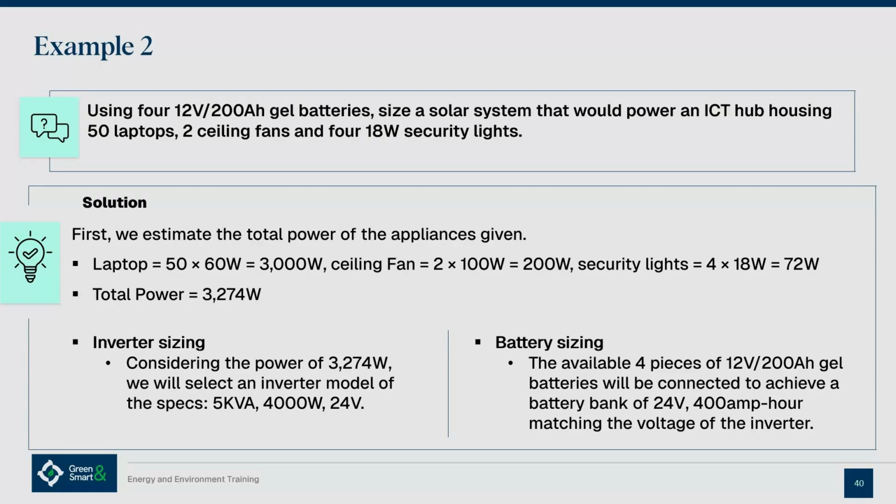This is done by linking the positive terminal of the first battery to the negative terminal of the second battery. This pair will now act as a single 24-volt battery with a capacity of 200 amp-hours. Repeat this process with the remaining 2 batteries to create a second, identical 24-volt 200 amp-hour pair. Next, you will connect the 2 pairs you created in parallel.